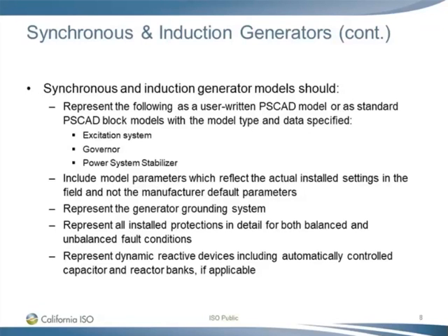The PSCAD model should also include model parameters which reflect the actual installed settings in the field and not manufacturer default parameters. The generator grounding system should also be represented, as well as all installed protection in detail for both balanced and unbalanced fault conditions. Finally, dynamic reactive devices should be represented, including automatically controlled capacitor and reactor banks if applicable. Next slide, please.